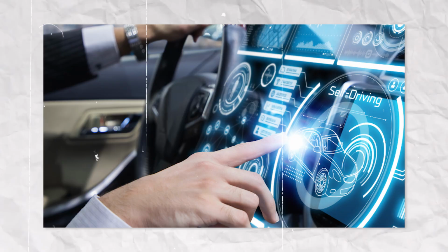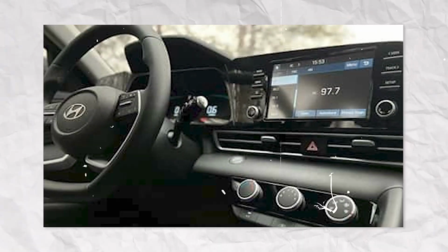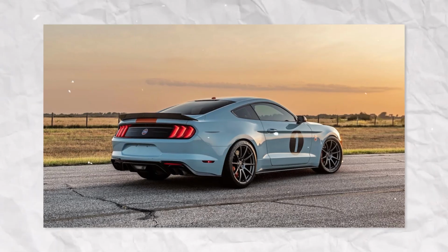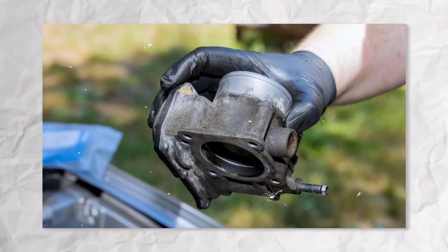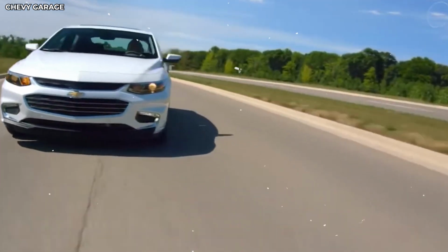He'd owned it for 2 years and 50,000 miles, almost all city commuting. He complained the truck felt slower than his friend's identical F-150, even though they had the same engine and specs. We performed the 30-second throttle reset procedure, then took it for an aggressive relearn drive. The difference was immediate and dramatic.